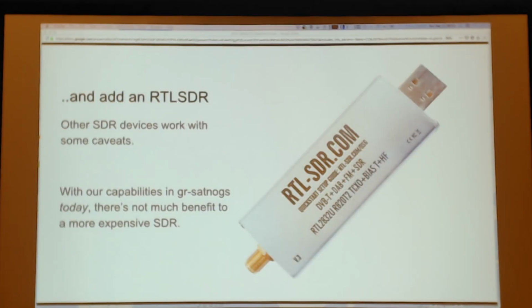The client software is Python, and the RF stack is GNU Radio. So it is possible to run this on any Linux desktop. We have people who do it. It's just not for the faint of heart. So it's easiest just to throw $35 at a Raspberry Pi and get it up and running and dedicate that to the client. We've got Raspberry Pi, add an RTL-SDR dongle. As Dan mentioned earlier, we do support most of the Osmo SDR supported dongles, soon to be the dongles supported by SoapySDR.